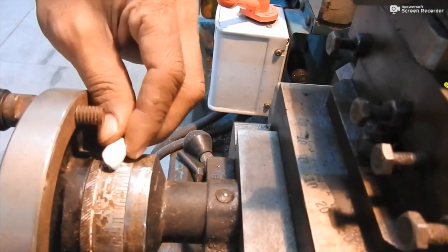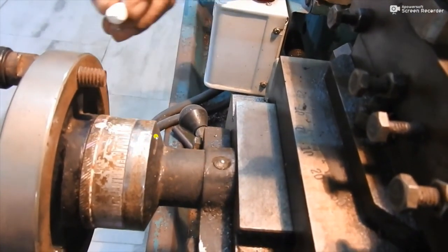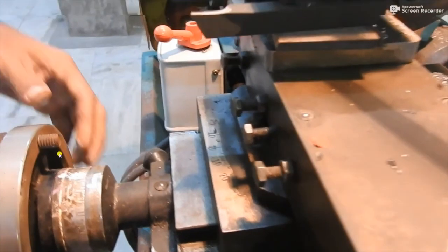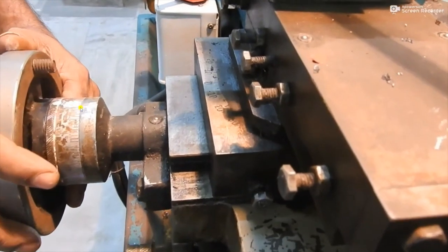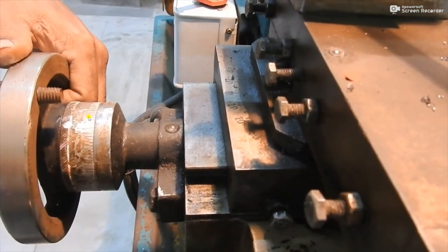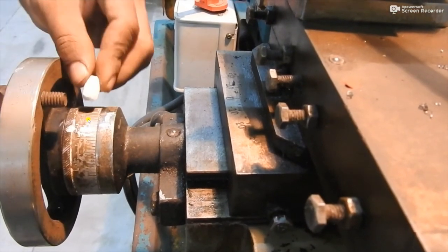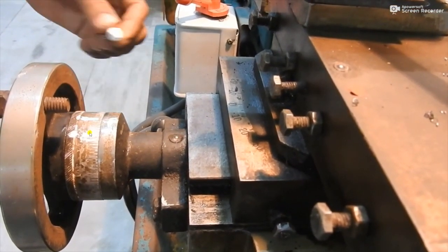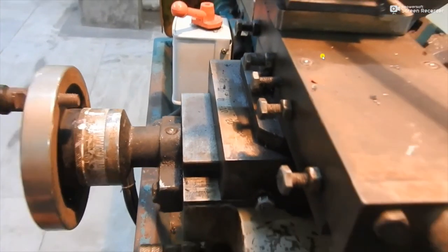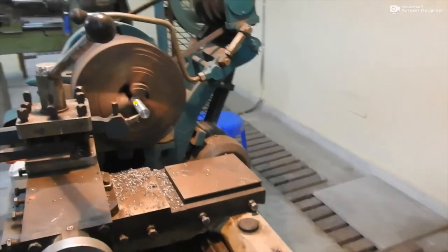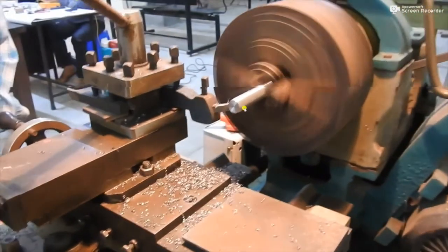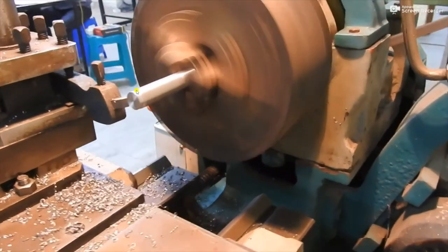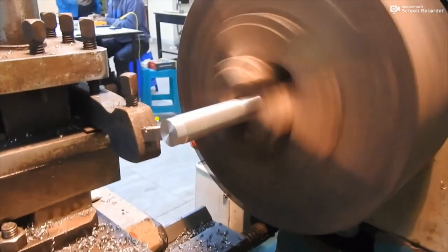The cutting tool can be moved along the cross direction, that will give the depth of cut. Let's consider it is the first position and we are rotating this wheel. Say we have rotated 10 small divisions, and we know one small division of this wheel means in the cross direction the tool will move 0.02 millimeter. So 10 divisions means 0.2 millimeter, and that's why the depth or penetration of the tool in the job is 0.2 millimeter.